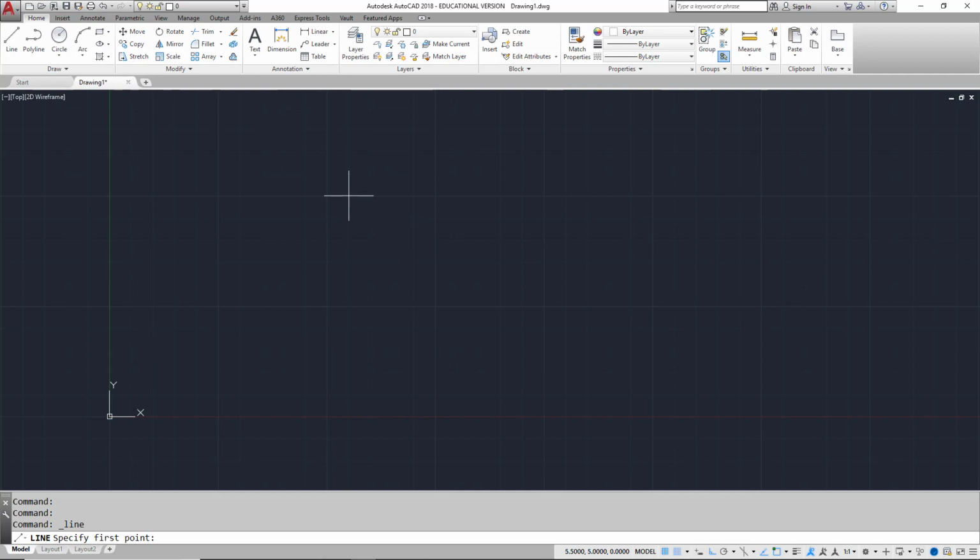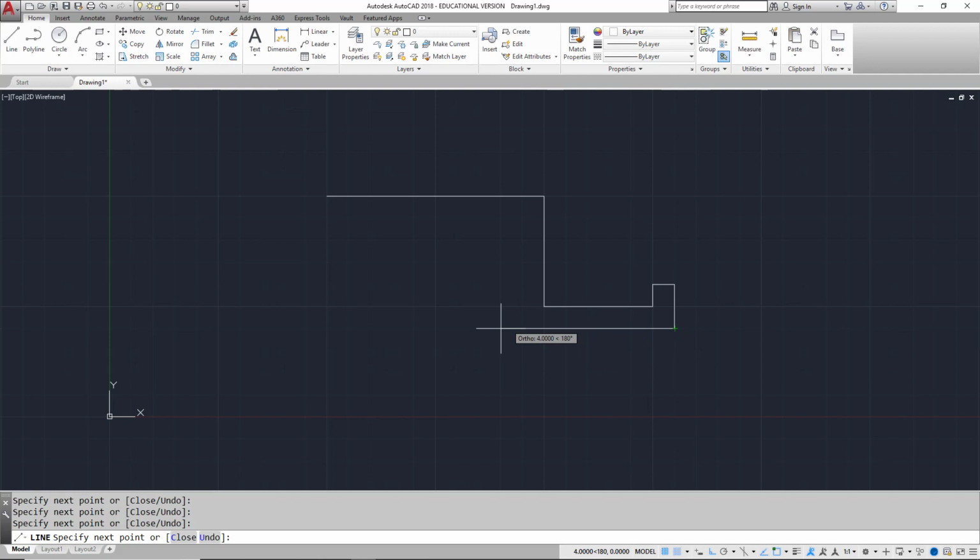But if I wanted to draw lines, it's very easy now to draw lines that are exactly those increments long. The smallest increment that I can draw is 1/2 inch. Now you can override that. If I wanted to go, say, 2 3/4, I could still stretch this out the direction I want to go, type in 2.75, enter, and now I've got a line there that's in between, but it's just a temporary override.